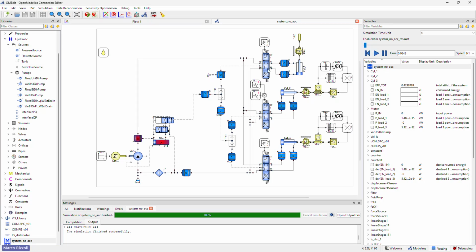We initially move the first distributor, and we go to extend the first cylinder. As I said, this is an unloaded actuator that is just taking 6 bar of load while the pump is under 13 bar. But this is because we just have a very big piston here that we need to extend, without really any power consumption.